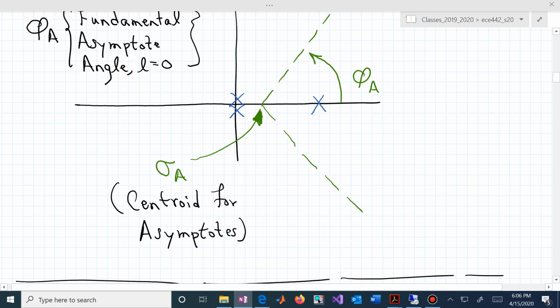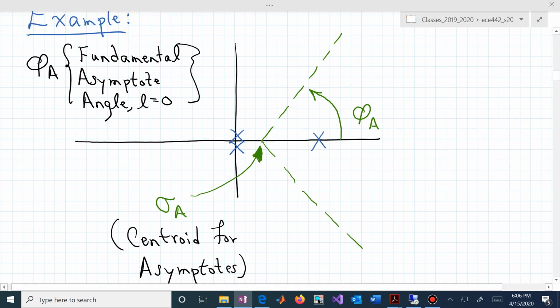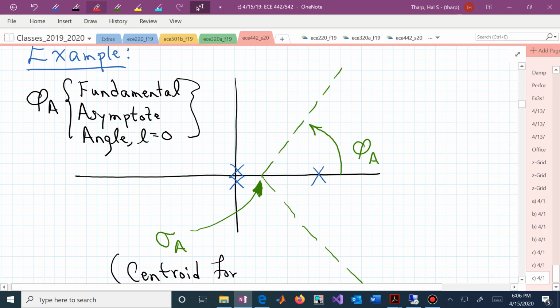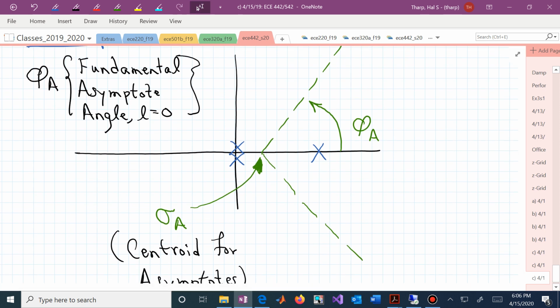This is then how we would create it. We now know how to draw the root locus with those asymptote lines as guidelines. Which line segments belong to the root locus? We have that line segment that actually possesses 2 branches, and we have this line segment. This one goes to the right, this one goes to the left.